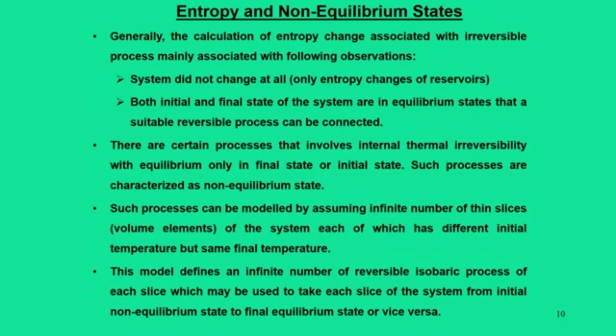If you recall, the integral of ln(a plus bx) dx is of the form (1 by b)(a plus bx) ln(a plus bx) minus x, and this form can be integrated, giving Cp ln Tf plus the T0 minus TL terms divided by T0 minus TL into T0.